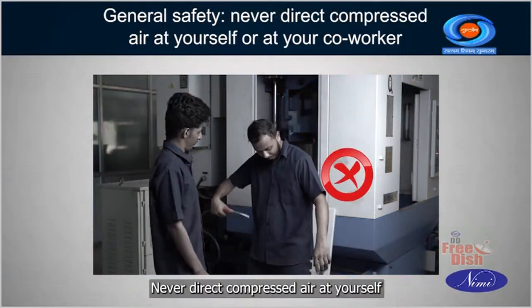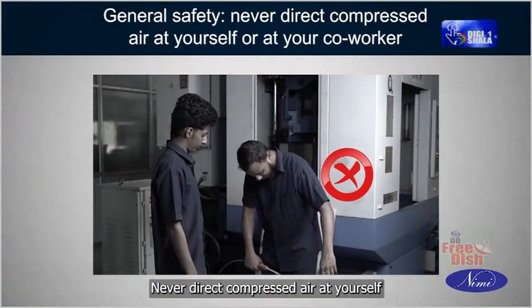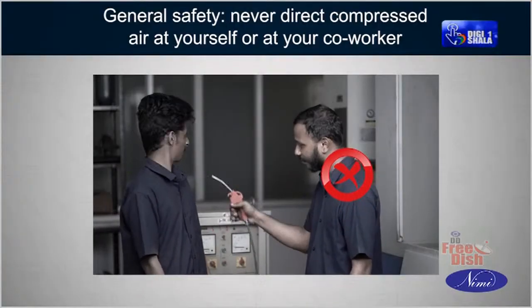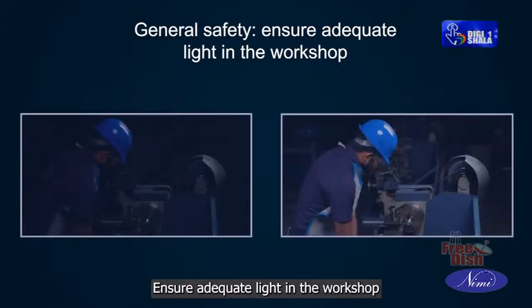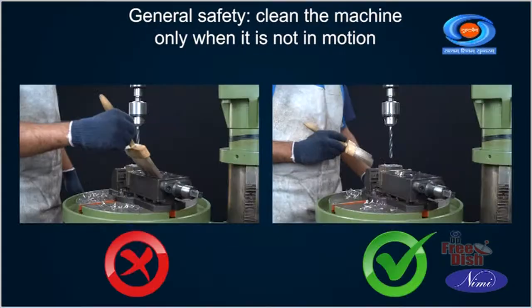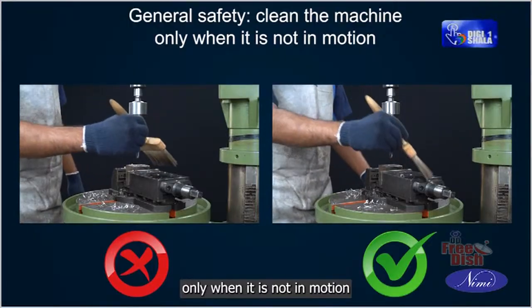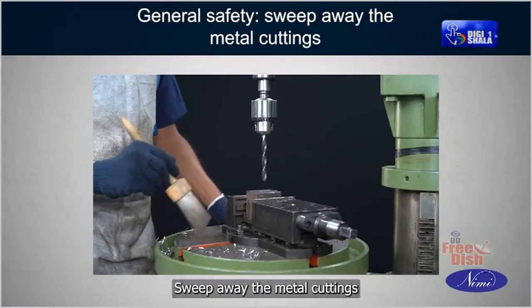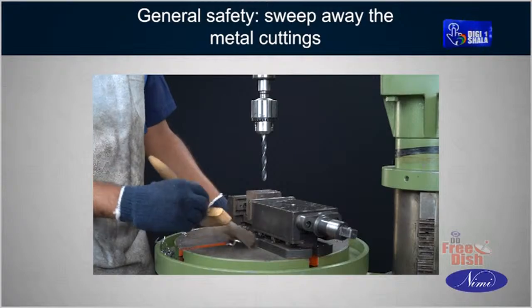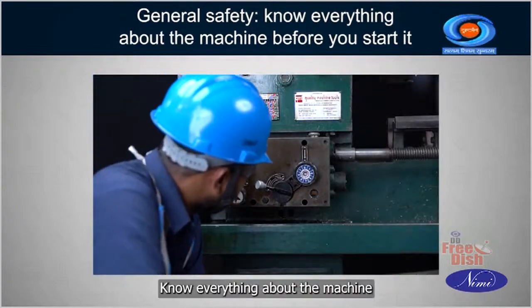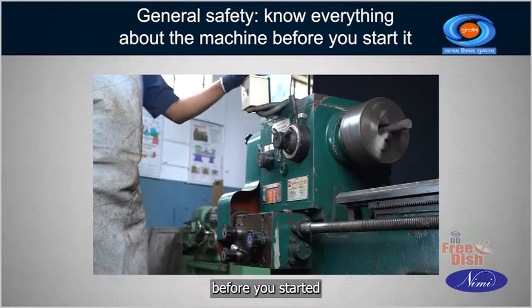Never direct compressed air at yourself or at your co-worker. Ensure adequate light in the workshop. Clean the machine only when it is not in motion. Sweep away the metal cuttings. Know everything about the machine before you start it.